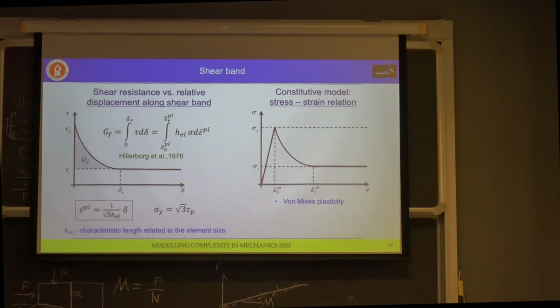And so we have here some volumetric law for this plasticity. We have here some effective strengths, which we introduce into Abaqus. Now, this relation actually can be applied to all the soil, yes, because as I talked earlier, each layer can have some different models. So if we are talking about the same model, it can be applied to all the soil, but right now what's more important is the shear band here.